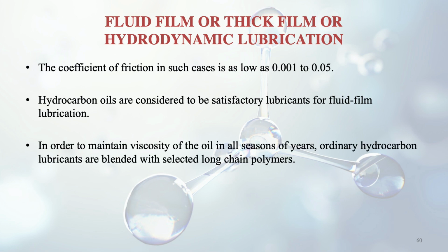And in order to maintain viscosity of the oil in all seasons of the year, ordinary hydrocarbon lubricants are blended with selected long chain polymers. You see, in winter it may happen that due to the temperature change, the viscosity of the oil becomes quite high and it becomes very thick, and the movement is hindered. So in that case we will have to add certain things so that the level of fluidity that we need is maintained.